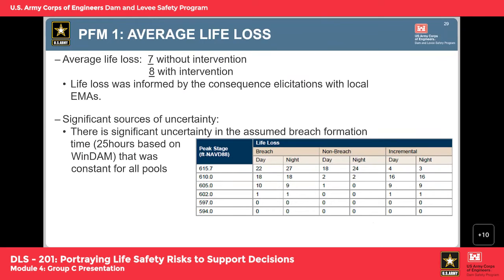Yeah, so there was discussion about the use of the tunnel because there's capacity there, but only up to a certain stage, at which point it would become overwhelmed. There's over 20,000 CFS in capacity, and it's usually operated around 3,000 CFS, so you can get some offset there to help reduce flows.